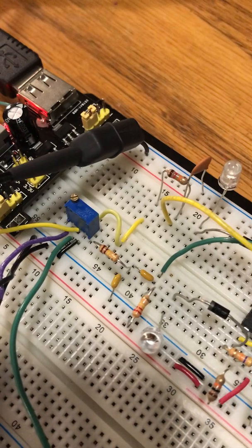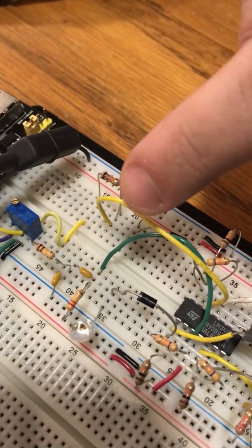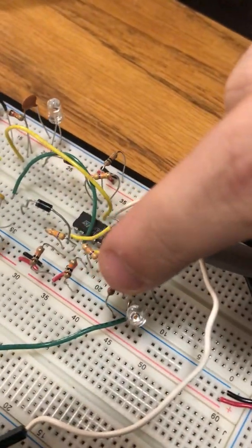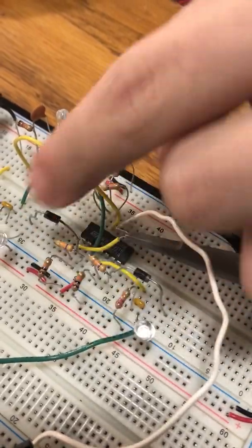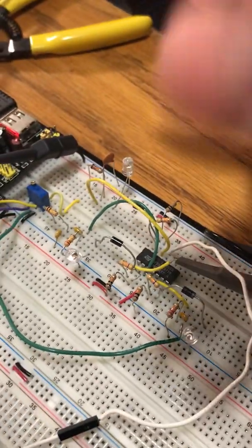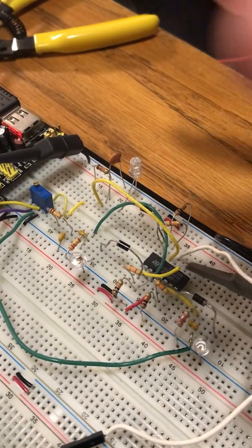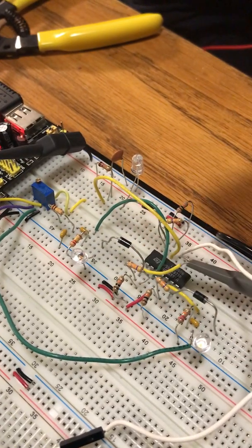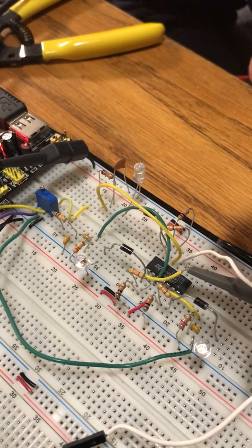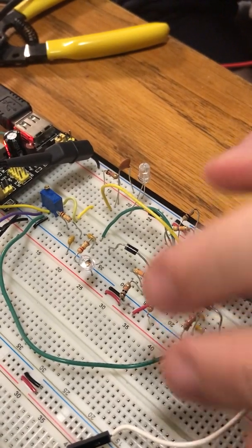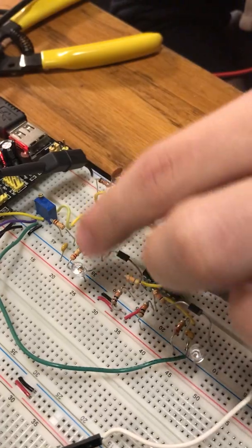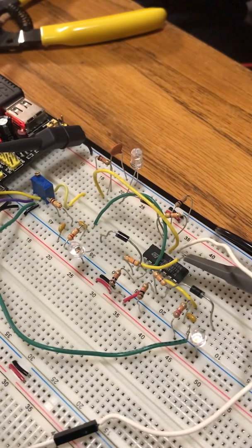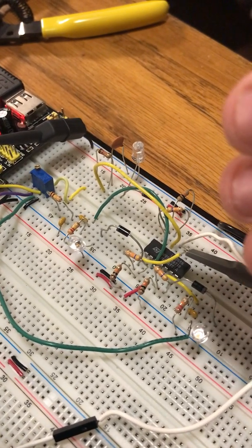Yeah. So over here, we're going to start off. We have a low pass filter, a band pass filter, and a high pass. High pass, band pass, low pass. Let's go through the structure of it first. We have the low pass, band pass, and high pass all getting the same input, and they all feed into their own individual op amps, corresponding with what quadrant of the circuit they're in. Then they each output into a diode, which outputs into an LED.